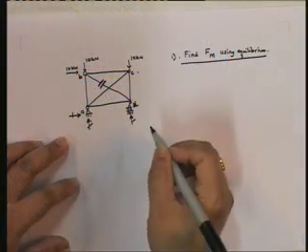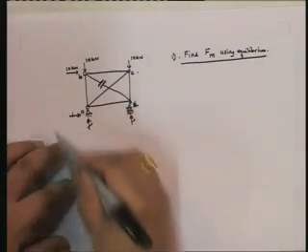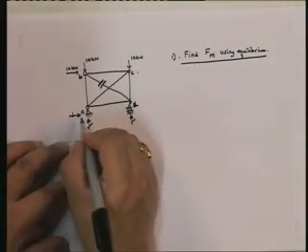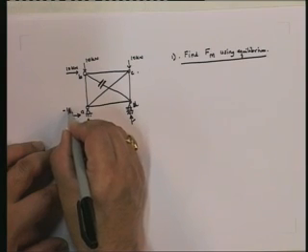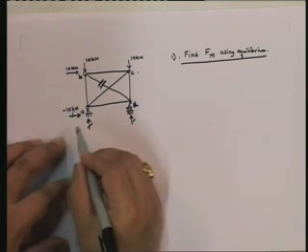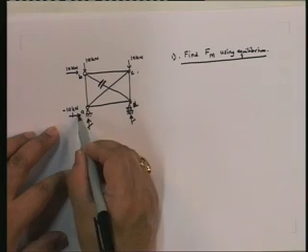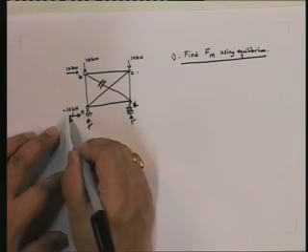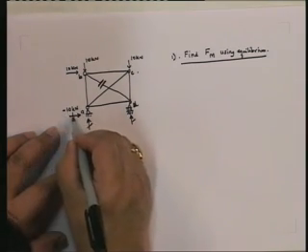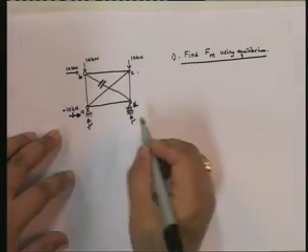And so I shall not go around specifically solving statically determinate structures and how to find out the forces in them. I'll make an assumption that you know all of those. However, in this particular case, I will actually go about solving. So I'll go through the steps without actually writing the steps down. First and foremost, these are the unknown reactions. So let us do sigma Fx equal to 0 of the entire structure. That gives me that this is equal to minus 10. In other words, the direction that I am showing is actually in the opposite direction, 10. So I am putting down minus 10 because I have shown it in this direction.